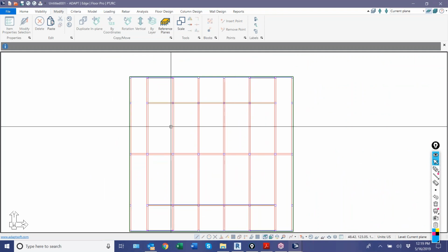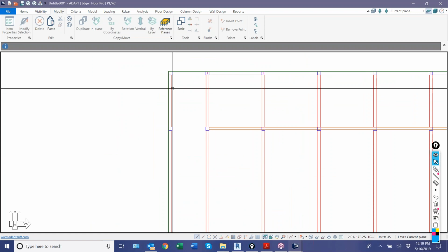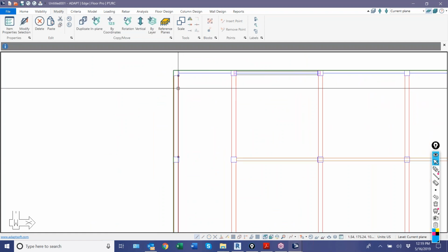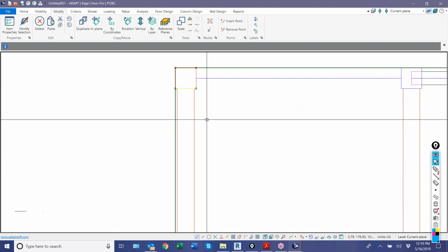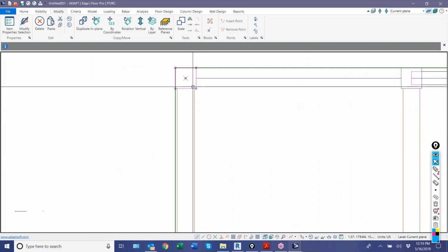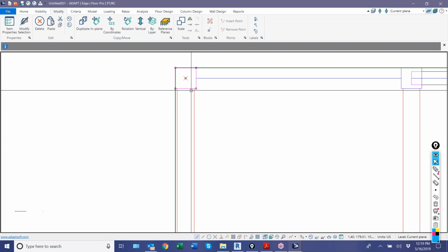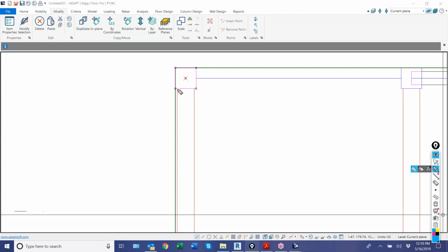Now the beams are a little bit more challenging, only because they're not a polygon. There's not a line that defines this side of the beam right here. So if I had a line, let's say here, and down on the opposite end, I could isolate all of the beams and then convert them to polygons and convert those to beams. In this case, that's not so.